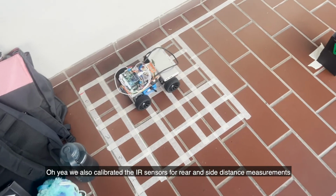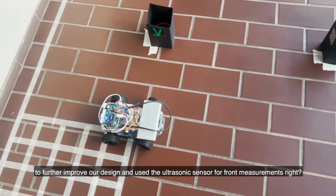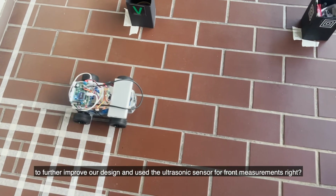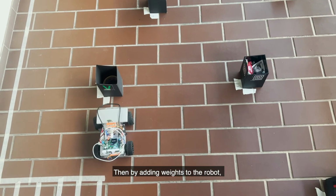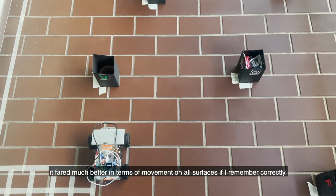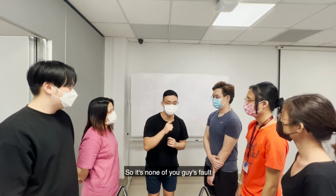Oh yeah, we also calibrated the IR sensors for rear and side distance measurements to further improve our design, and use the ultrasonic sensor for front measurements, right? Then by adding weights to the robot, it fared much better in terms of movement on all surfaces, if I remember correctly. So it's none of you guys' fault.